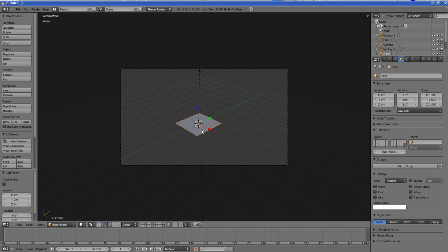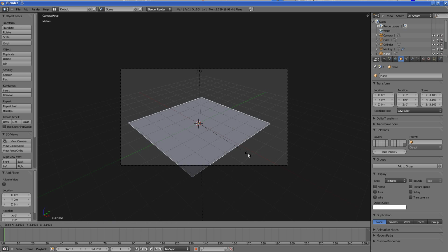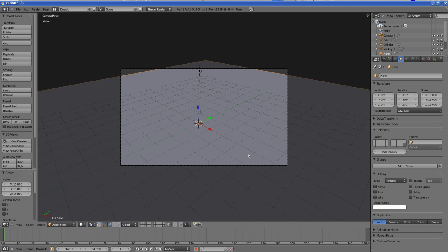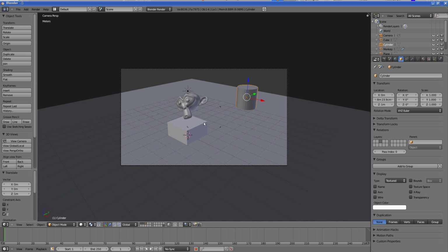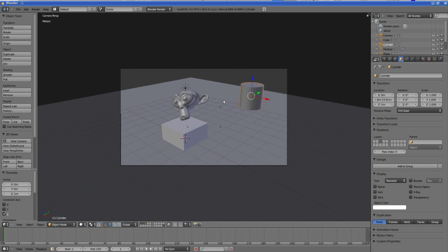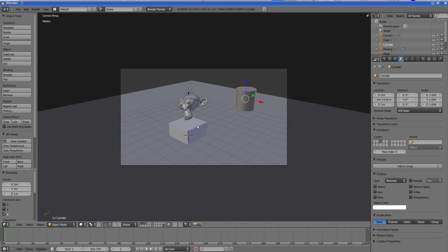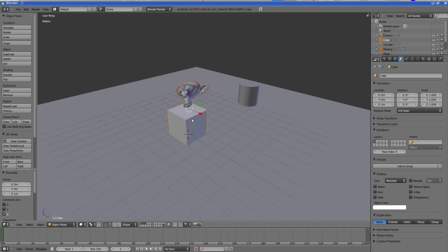So select it, then S to scale. Uniform scale, and let's type a value of 15. And see how the objects are. I'll need to move the cylinder G Z 1. Then Shift F to fly, and move the scroll wheel on your mouse to adjust. Let's select these two and G Z 1. So now everything rests on the ground plane.